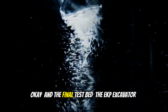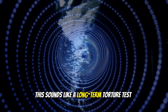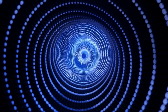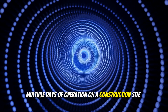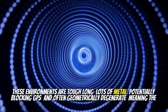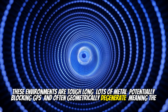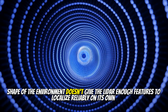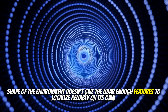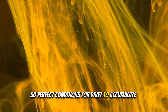Okay, and the final test bed, the excavator. This sounds like a long-term torture test. It really was. Multiple days of operation on a construction site. These environments are tough, lots of metal, potentially blocking GPS, and often geometrically degenerate, meaning the shape of the environment doesn't give the LiDAR enough features to localize reliably on its own. So perfect conditions for drift to accumulate.